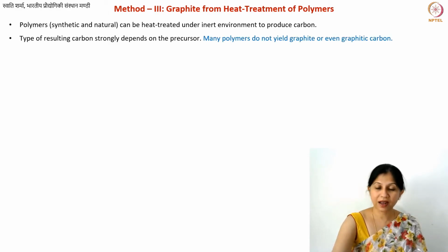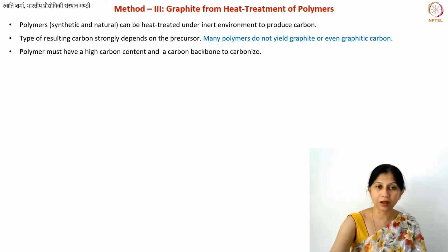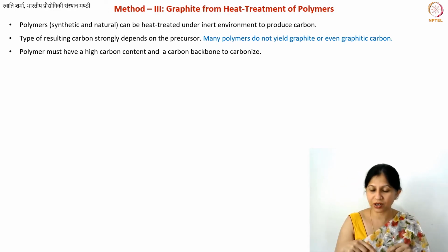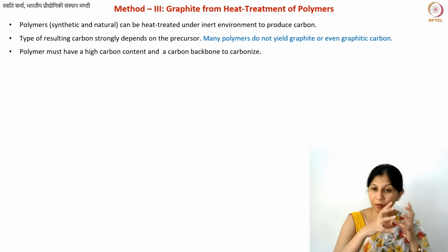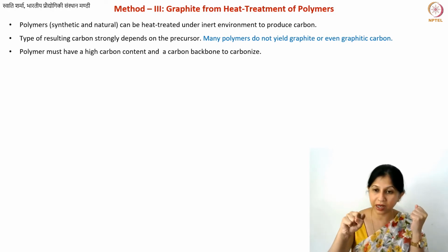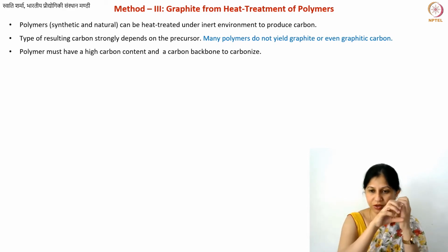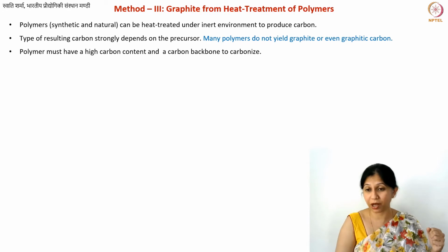As I mentioned, you should have certain anisotropy which helps. Or what you can also have is an aromatic backbone, but this may not always work. What aromatic backbone means: you have aromatic structures, so ring-like structures. And the backbone of a polymer means the primary structure of the polymer. On the sides you can have something else, but this is the backbone, what is called the primary structure of the polymer.